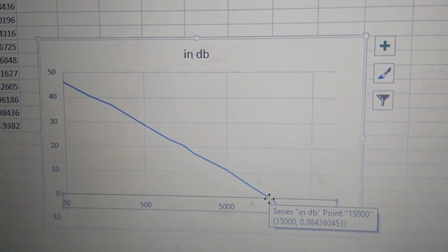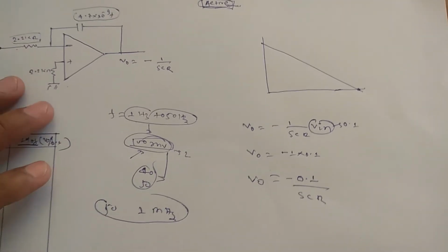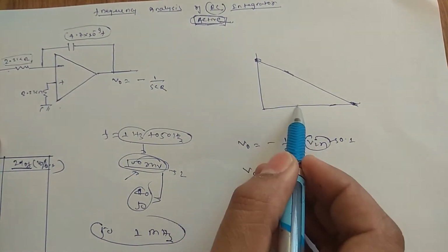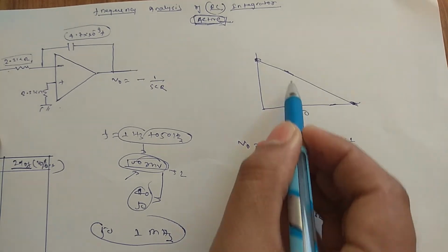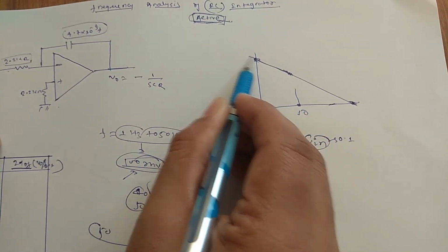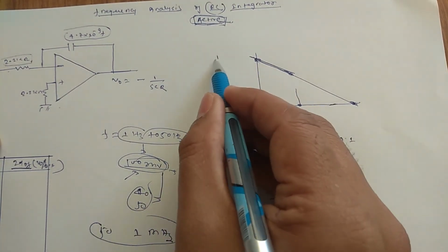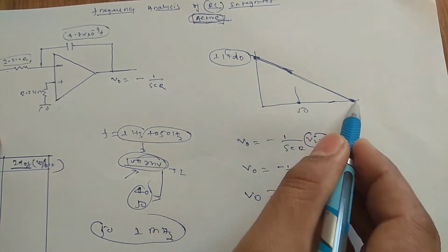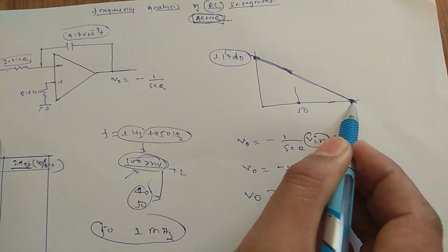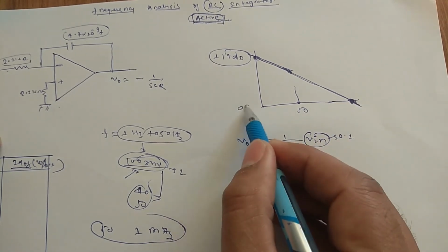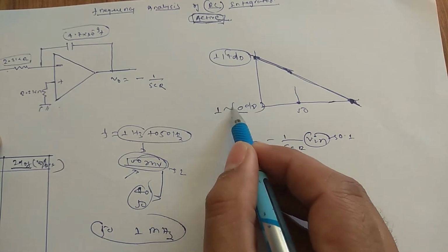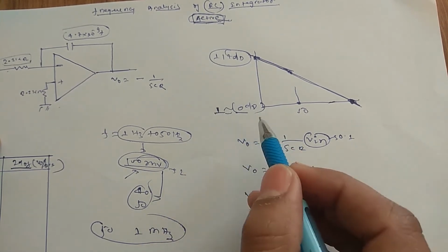So, going to the DSO. Now before going to the DSO, let us think about this point and this point. I told you we have started from 50 Hz, and there was this one. Now I have extrapolated, and this is certainly going to cut your open loop gain. This is around 114 dB for this IC. Now what will be this point? This is a point of concern where our gain is unity. This is your 0 dB.